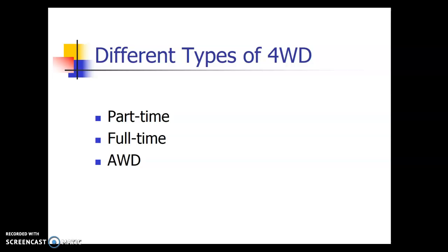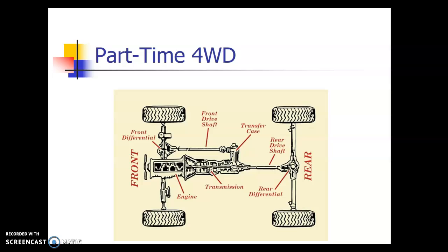All-wheel drive is kind of like full-time four-wheel drive, but you don't get low range. Think of cars like an all-wheel drive Quattro, right? They don't need to lock it in low. They're not crawling out of a rock garden of some sort. So that's all-wheel drive. Again, we'll elaborate, starting with part-time four-wheel drive.